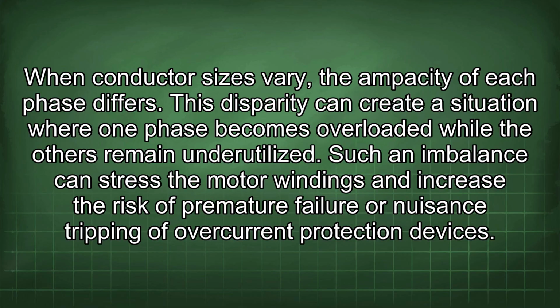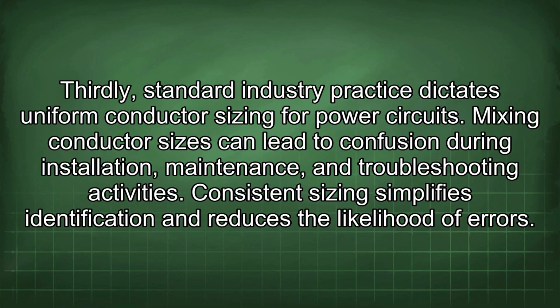Thirdly, standard industry practice dictates uniform conductor sizing for power circuits. Mixing conductor sizes can lead to confusion during installation, maintenance, and troubleshooting activities. Consistent sizing simplifies identification and reduces the likelihood of errors.